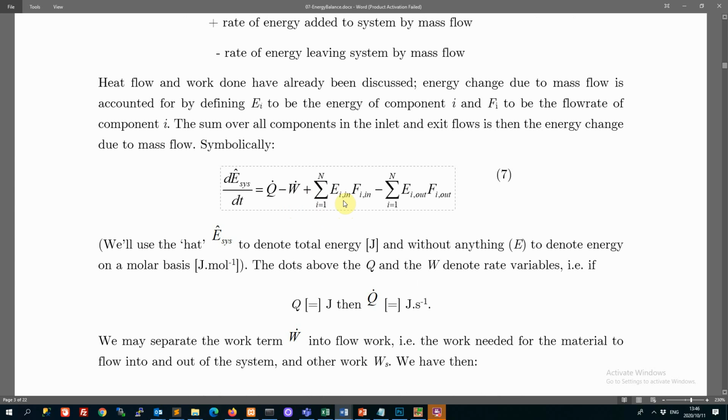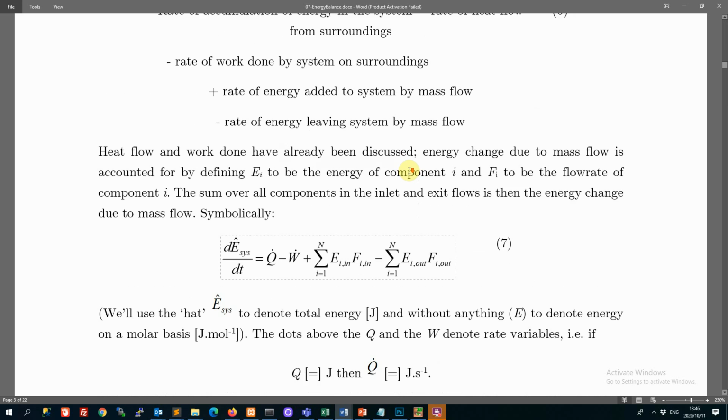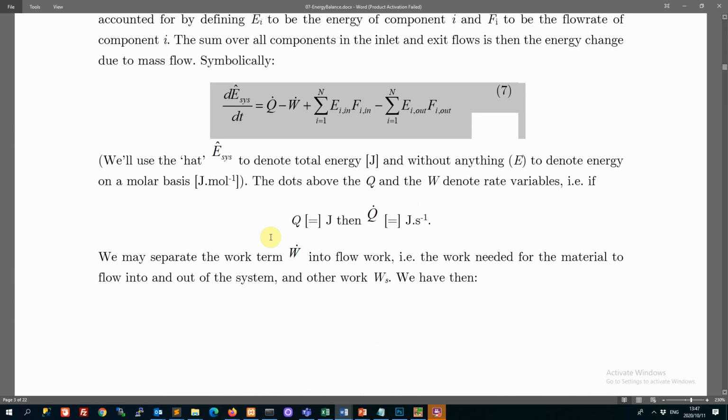And then, as we said, the other forms of energy, just the flow. So the chemical, if you like, this is the chemical energy. So you've got chemical energy flowing into and out of the reactor. So no reaction terms as yet. This is just taking a straightforward view of the system. If you have a boundary here, what are all the energy contributions to that system? And those are all the energy contributions to that system. So that it looks like a nice strict energy balance. It's leaving very little room for doubt here.